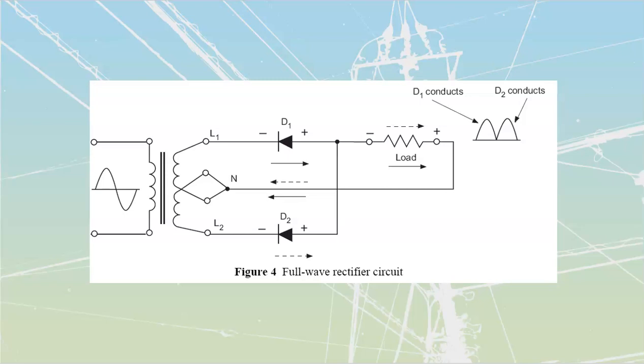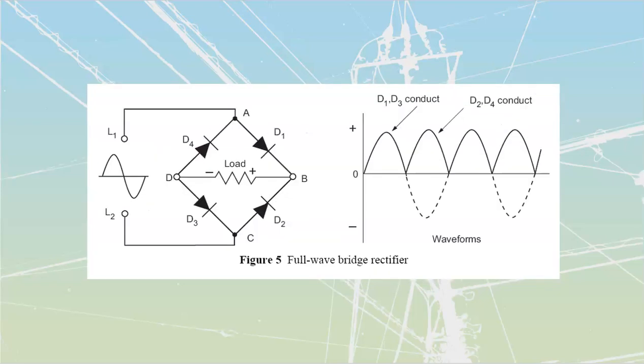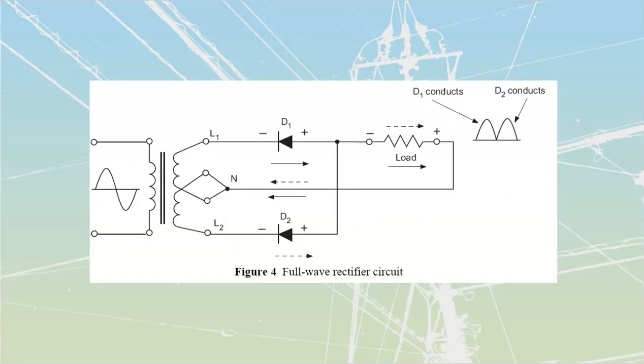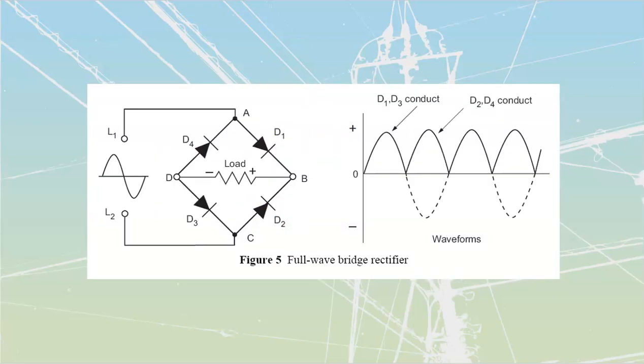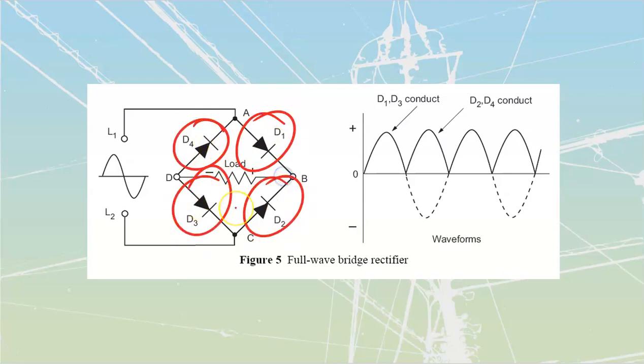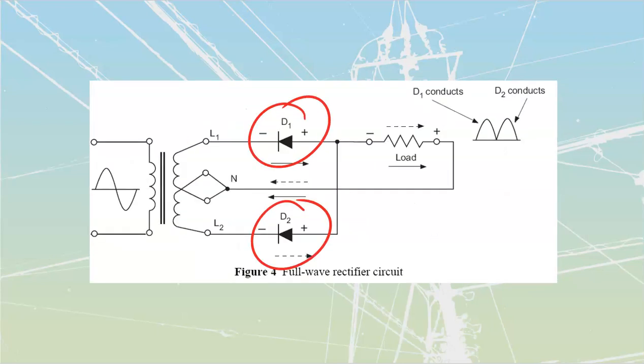Now, the biphase type of rectifier has some benefits over the next rectifier we're going to look at, which is the bridge rectifier. The biphase has only 2 diodes. The full wave, which is the other way that we can do this, is going to have 4 diodes inside of it. So the full wave requires more diodes. But my biphase also requires the use of a transformer.